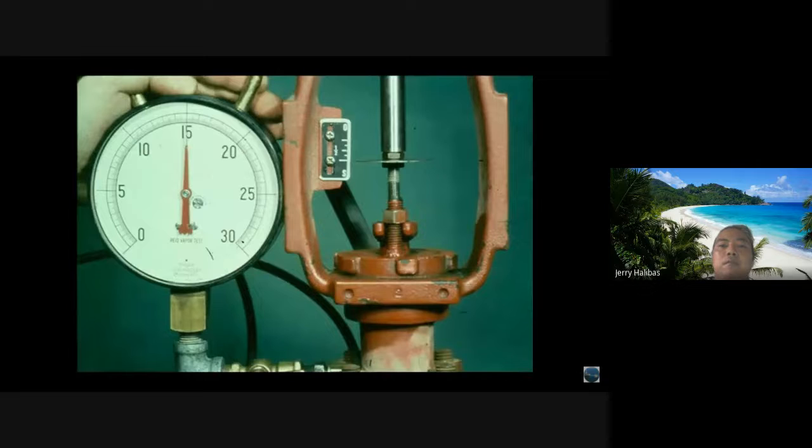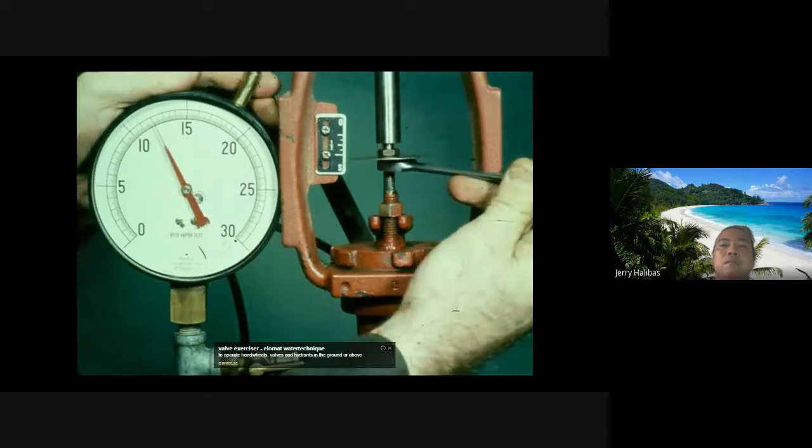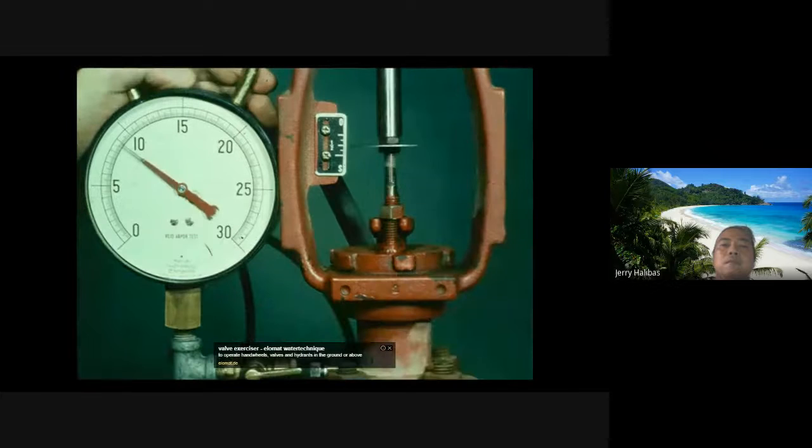Make adjustments if necessary. You should make the valve barely seat at 15 psi. Then lower the pressure and screw the plug stem out 2 revolutions. Then lock the lock nuts. Check the valve for hysteresis. Then commission it.